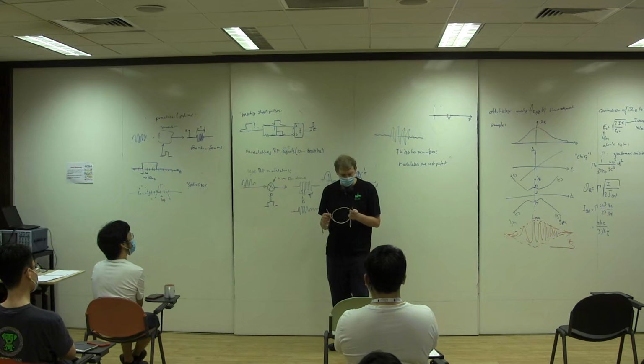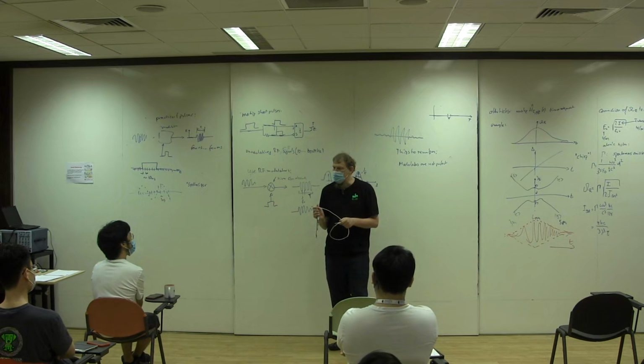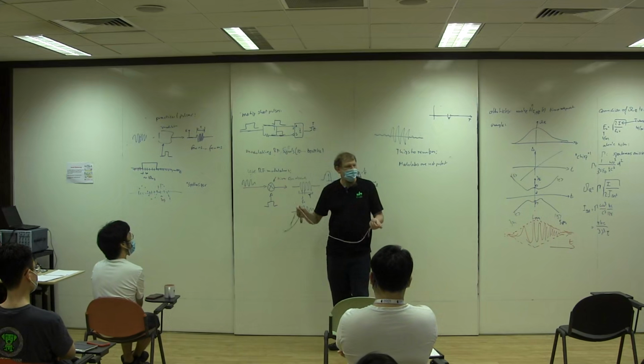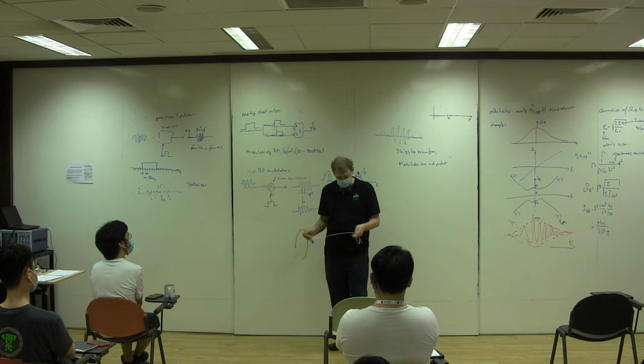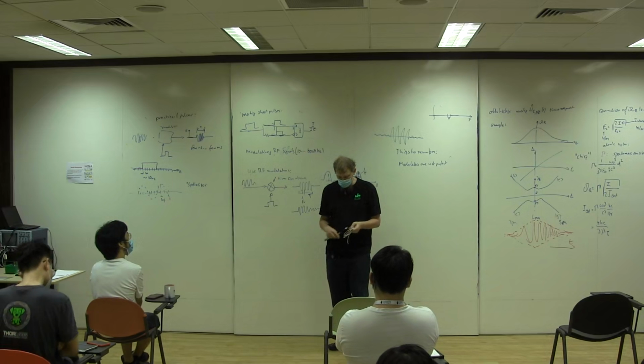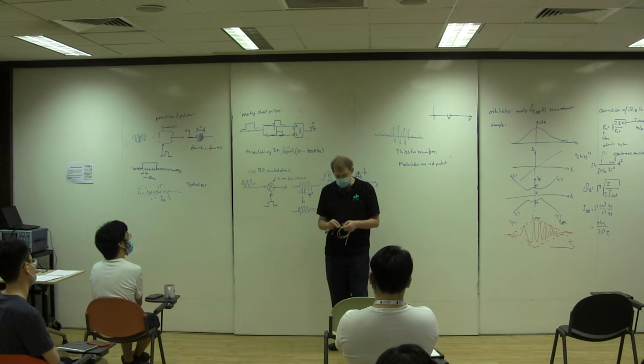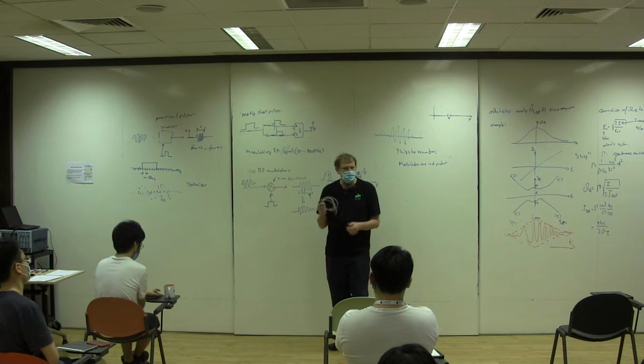which means just in order to get a simple signal from A to B, you need to send a power of about half a watt. Okay, just to switch something on and off, and that's typically a power that is larger than what you can get out of the digital circuitry that's around. So you need to think of how do you bring your signals from A to B.